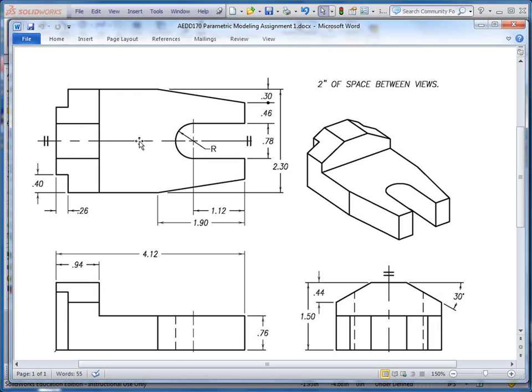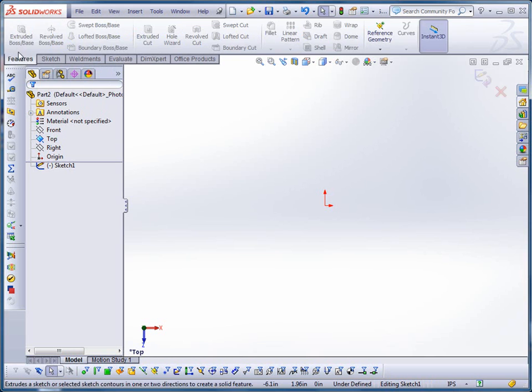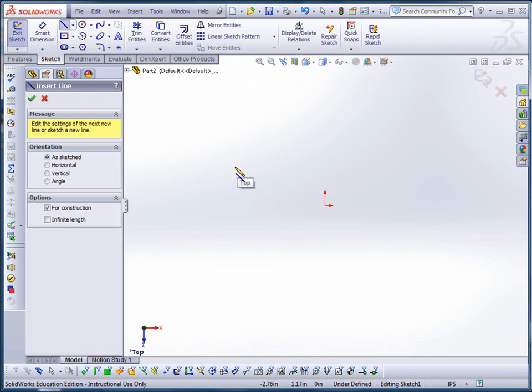So I'm going to start by drawing in a symmetry line, and in SolidWorks that's known as a center line. And then I'm going to sketch from here up to that corner, over to here, down to that point, down here, and then bring a line back, and I'm going to put a circle in. So first I go up to the command manager for sketching, which is now shown in blue. Features have tools that are shown in yellow and green. So I'm starting with a sketch. There's the line command. Arrow beside it gives me another choice. I'm going to select center line, and once I pick center line, I'm just going to line up my cursor with the origin.